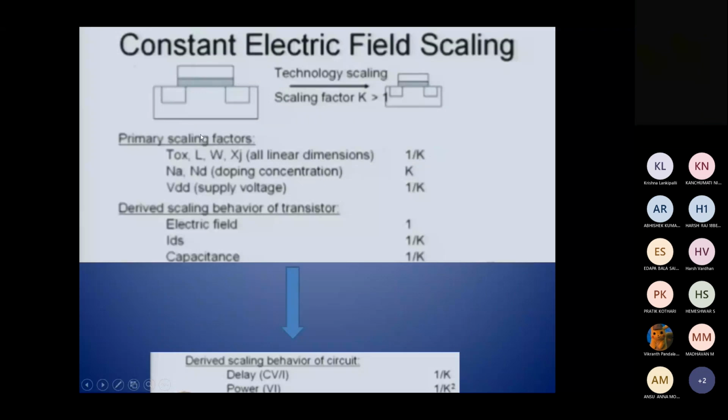Okay. So if you can see here, in this MOS device, we have a source, we have a drain, the oxide thickness is here, and we have a gate electrode over it. If it is an NMOS transistor, we have a P-type substrate. Similarly, in the miniaturized version, we have a source and drain, and for an NMOS transistor we have N plus here and N plus here.